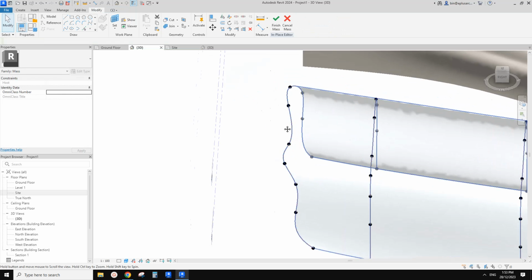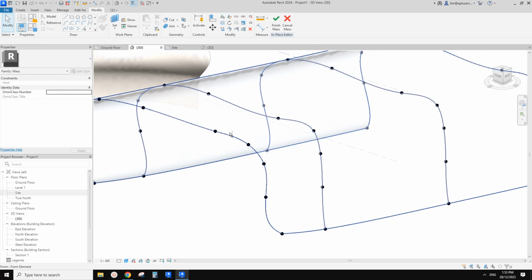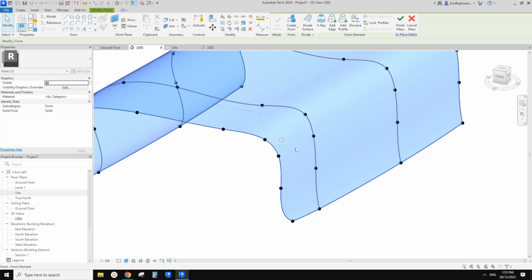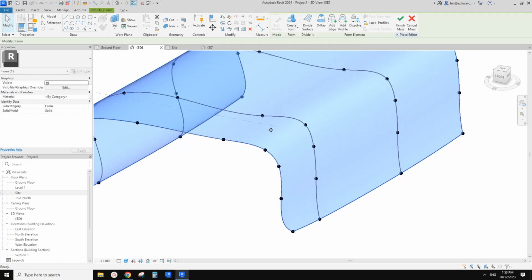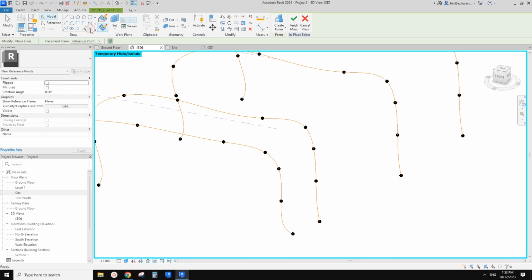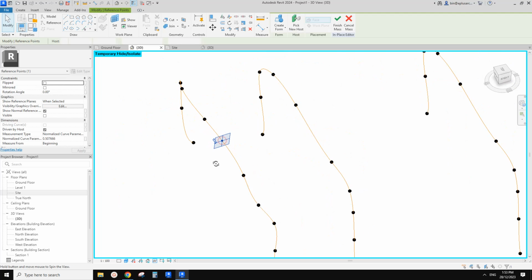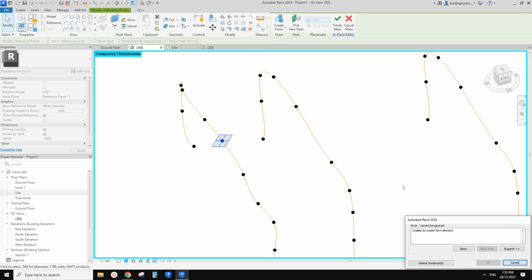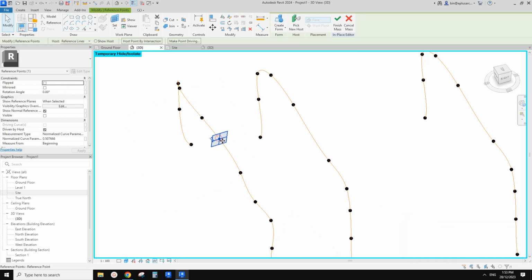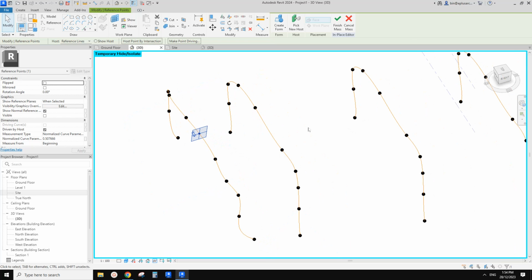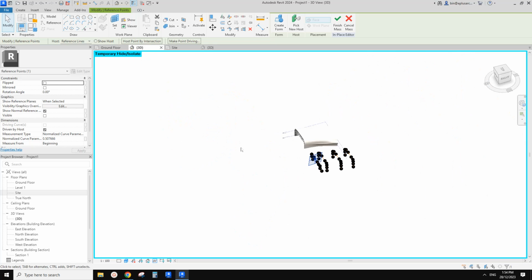Right, so this, and how can you add points? So you do it this way. So let's just hide the surface. So you can place a point, use draw on face, okay, and place onto this reference line, and then select this point, and then you can use make point driving. So this will allow you to, sometimes this will happen, so it means it will change this reference line a little bit, and then sometimes it will cause this mass, the surface, to fail. So just be